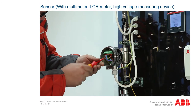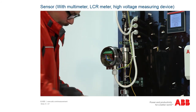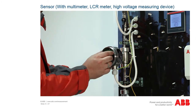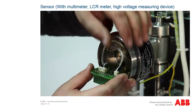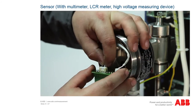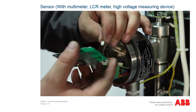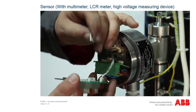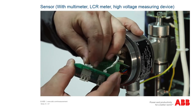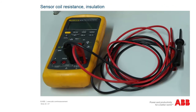To do this, remove the sensor PCB and disconnect the PCB connectors, the 3-pin electrode connector, and the 2-pin coil connector at the rear. Proceed with caution and make sure that you do not damage the connectors. Now insert both connectors in the female connectors on the XE board. This board has the advantage that the connector contacts are run on large terminals, which makes measuring the following steps easier.